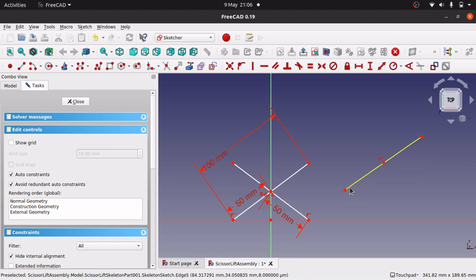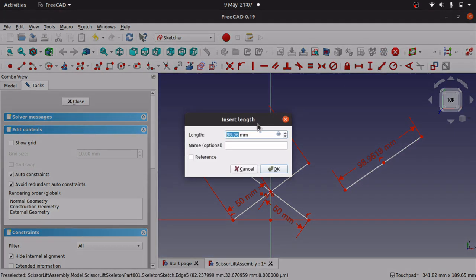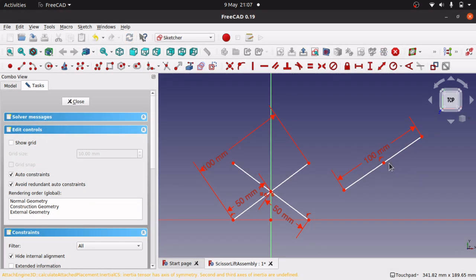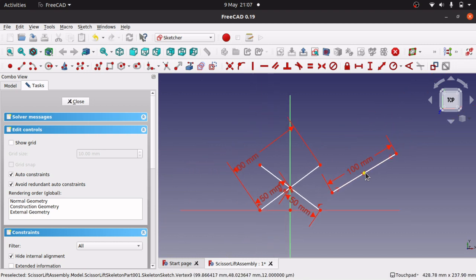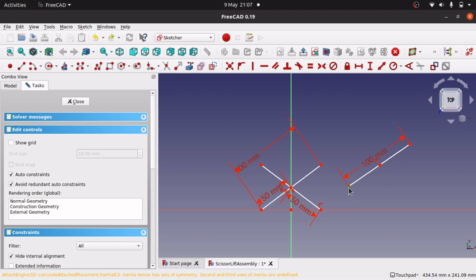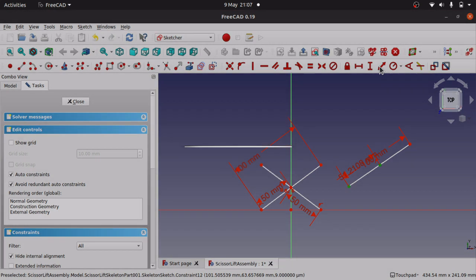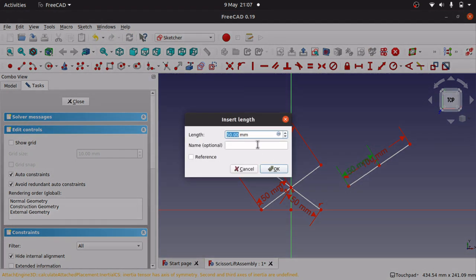And what I would do is take this length, set as a length of say 100 millimeters, and then making sure that one's in the middle, we could use a symmetry constraint by clicking those two and clicking that middle point and doing a symmetry constraint on that, and that's placed it in the middle like so. Or like I've done here, I've used a constraint of a length which is half of this one, so I can place a length in there and make that 50 millimeters,